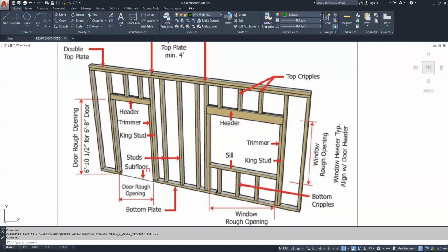The door or windows, when you're putting them in, should not be jammed in there so tightly that you're kicking and punching them to try to get them in the opening. If you're doing that, you know something's wrong. It should go into the opening, and there will be a gap around it. The gap lets us make sure that the window or door is perfectly square, perfectly level, so that the window or door will operate correctly. They'll open up and shut correctly.